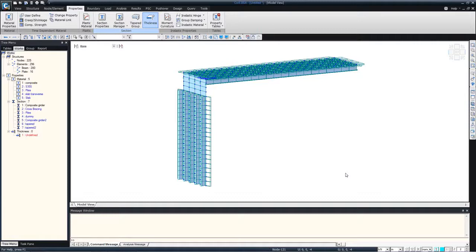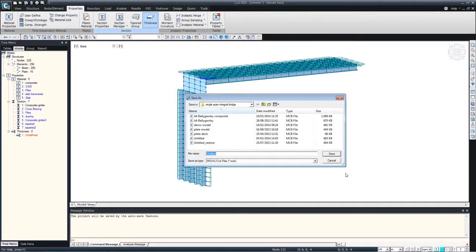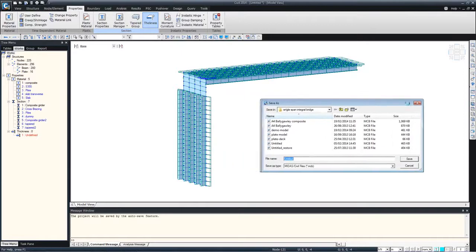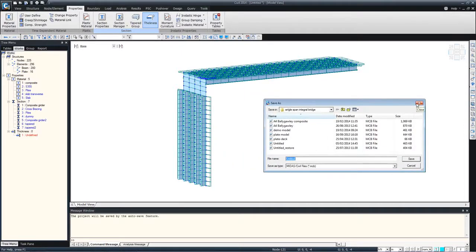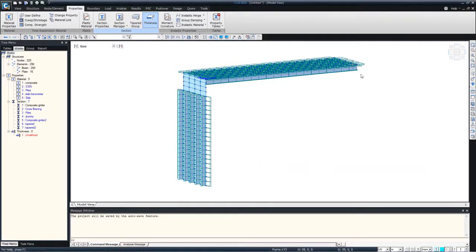Yes, one way is that you cannot import splines or arcs directly, but you can break them into lines, into further segments, and import them. Sometimes you can also use polylines, but I would not recommend using polylines every time, because polylines can have some problems with the intersection. It is always good to use lines whenever you have to generate arcs or any other type of geometry. So always break your arc into several segments and import them into Midas Civil, because the software directly deals with mesh.